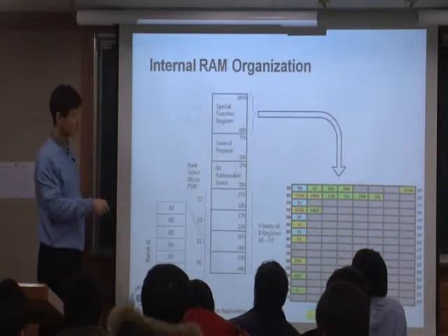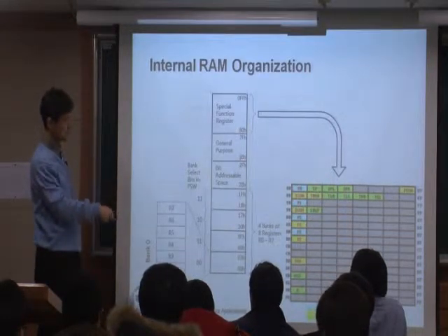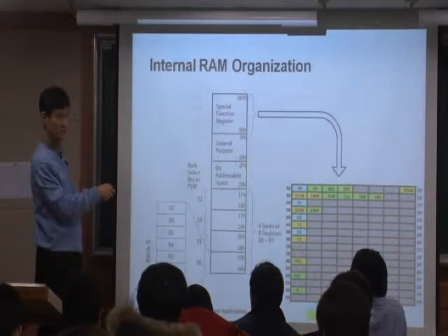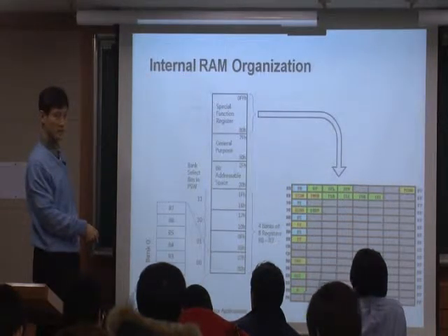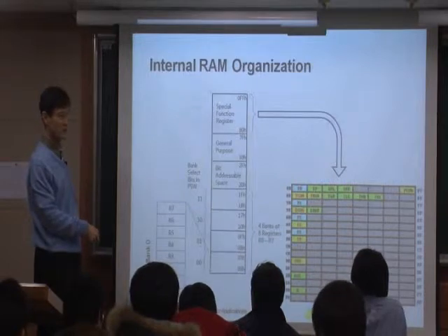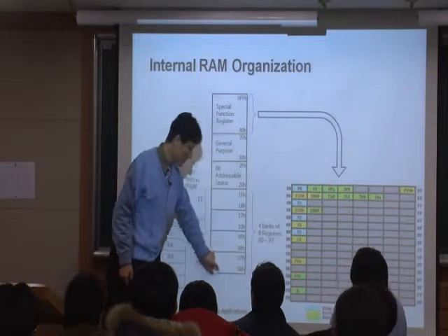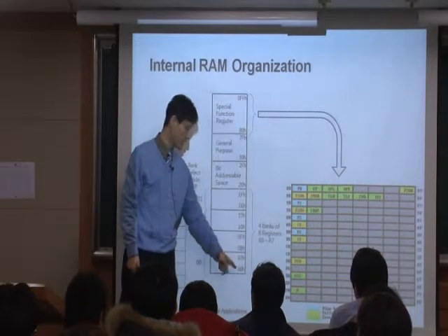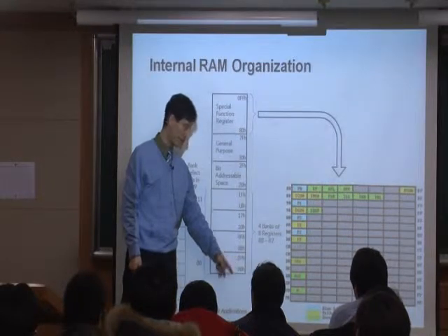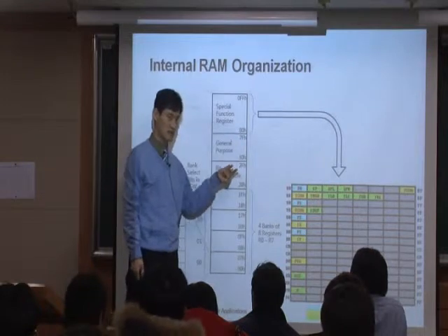Generally, what is an address, by the way? This is the address, 00 to FF. But each address is for one byte. This is a byte address. You have an address 00, and that means you have 1 byte at 00. If you increment the address to 01, then it's the next byte. It's a byte by byte address.